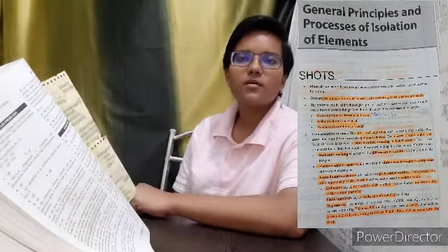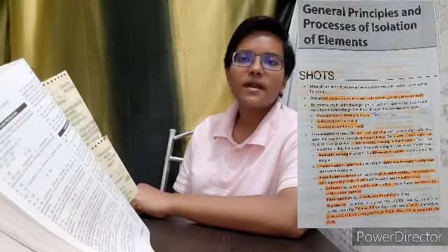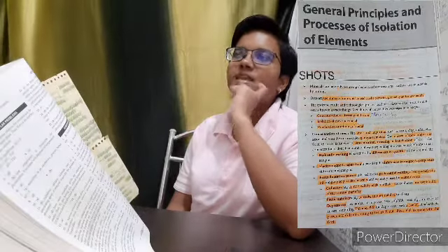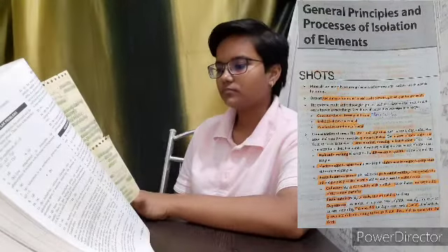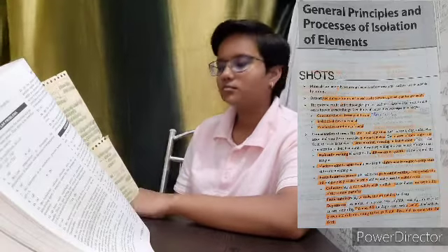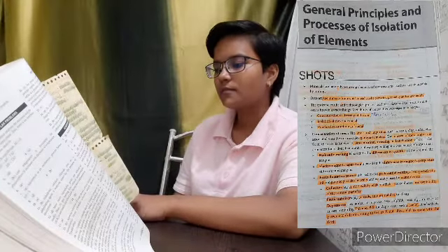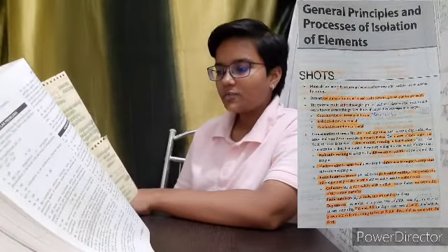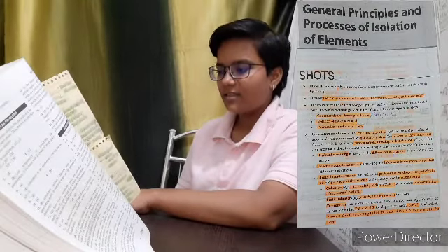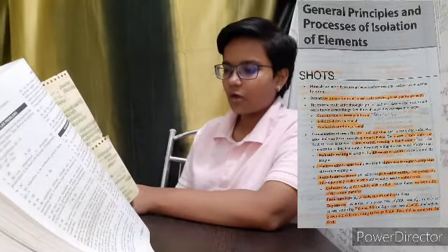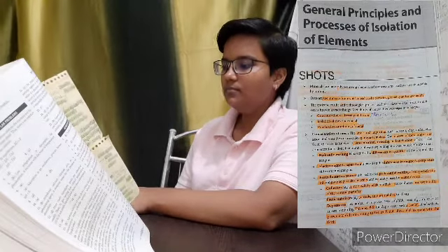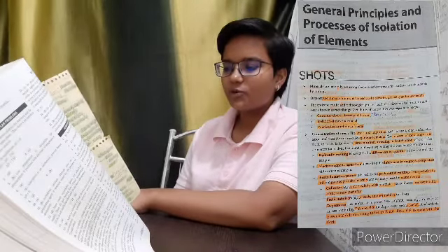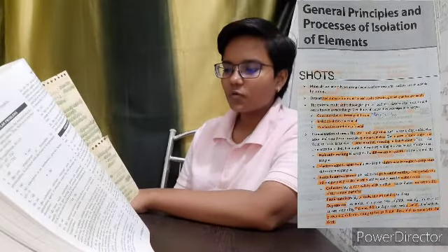Preferential wetting of gangue particles by water and ore particles by oil: ore by oil and gangue by water. It is mainly done for sulfide ores. Collectors, pine oil, fatty acids and xanthates enhance non-wettability of mineral particles. Froth stabilizers, cresols and aniline, stabilize the froth.